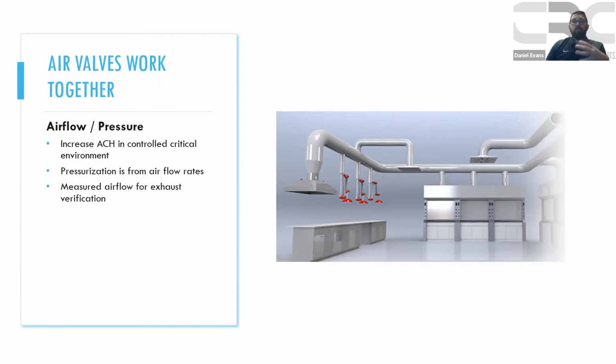The reason being is we have a lot of exhaust that comes in these spaces. And if I don't know what one's doing, or there's one out there that we're going to assume does 100 CFM, but maybe it's doing 120, or maybe it's doing 90, now that impacts my entire volume in, volume out. We want to be able to measure and validate pressure. We're obviously controlling to CFM rates in our tracking, but we want to know that we have pressure there.